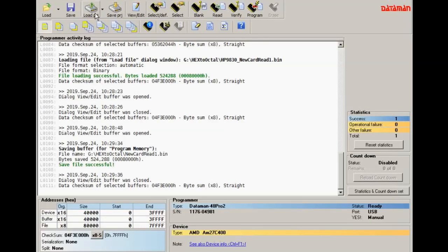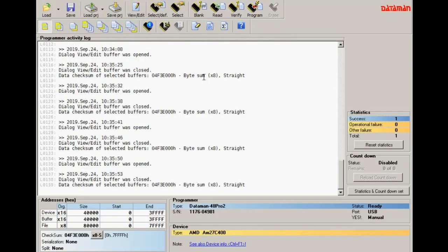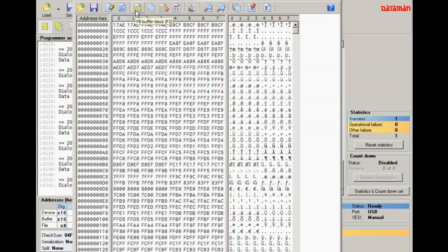If we go back to the programmer, one of the main issues, of course, with a card like this, because of the odd decoding, is making errors in the decoding logic. Okay, if we go back to the buffer, you may recall from previous videos that there were certain key values I was looking at. One of the issues with this card is the odd address decoding. So it is important that I check that it can properly decode all the way through the various blocks of EEPROM, because it is odd the way that that decoding is done. It looks good so far because we haven't seen any errors when the output file is compared against the file that was used to generate the code for the ROM.